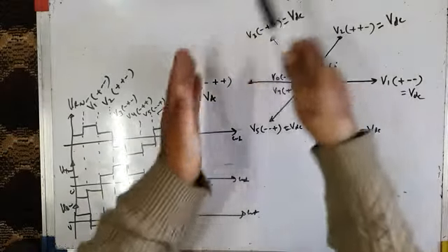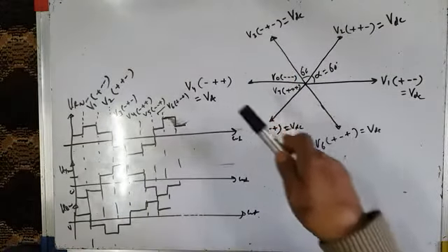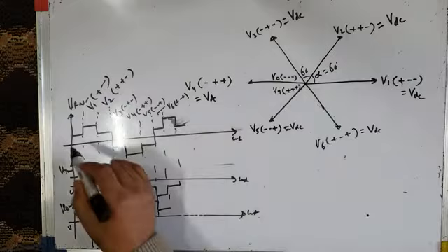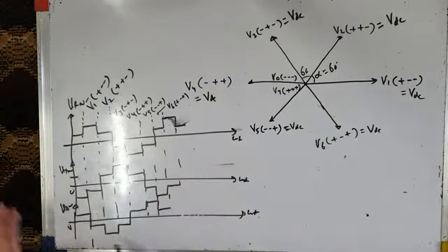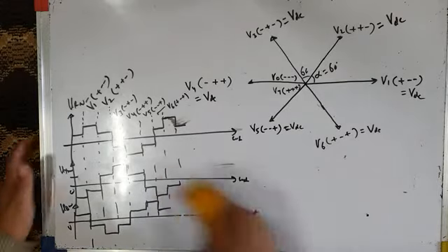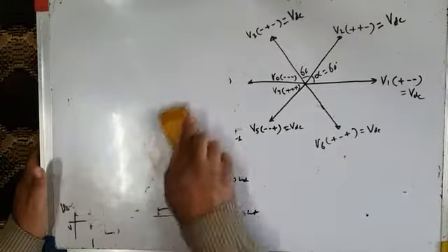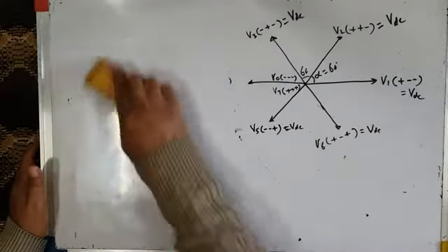And these voltage vectors which get applied across the load after every 60-degree interval in the three-phase reference frame represent three-phase 6-step voltage waveforms like this. Is that clear? Now, our aim is that we don't want this type of voltage across the load.